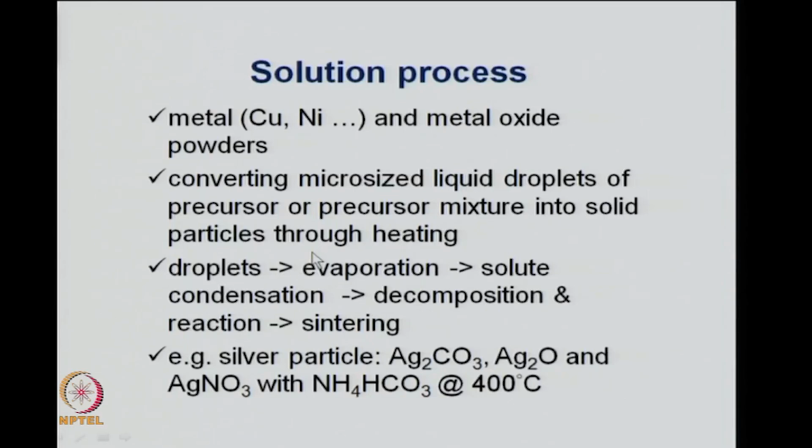The process can then be divided into steps. You have liquid droplets, typically water, containing the solute particles, which on evaporation give you solutes which condense. After condensation they can decompose, and if they are able to decompose, they will decompose at higher temperature, leaving behind the oxide or the metal or metal sulfide.